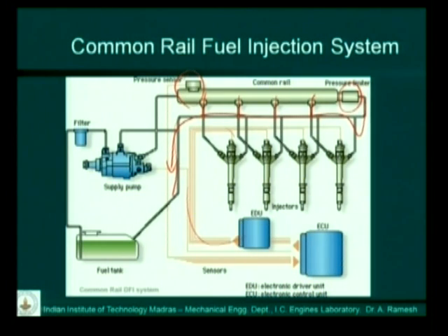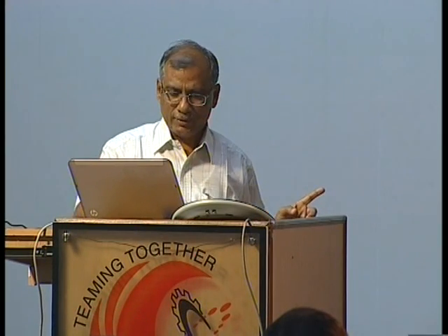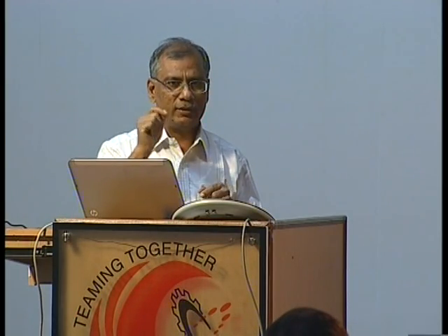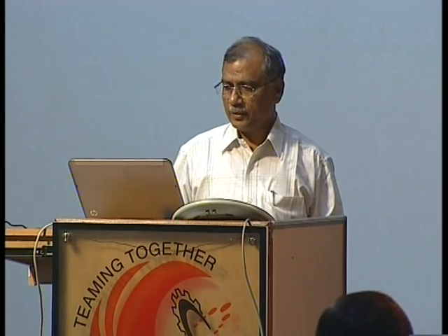It's a very simple system. In fact, it is simpler than the mechanical system. You simply pump the fuel into a rail and extract the fuel from the rail. It's like a reservoir, you are tapping the fuel. And the most important thing is the injector, where you control the injection process. So is this system clear? We will now go to the working of the injector, because that is the most important thing.